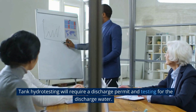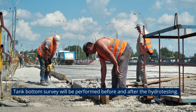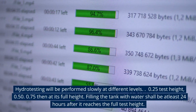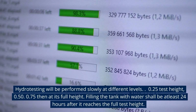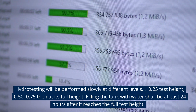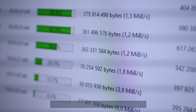Tank hydrotesting will require a discharge permit and testing for the discharge water. Tank bottom survey will be performed before and after the hydrotesting. Hydrotesting will be performed slowly at different levels: 0.25 test height, 0.50, 0.75, then at its full height. The tank shall be held filled for at least 24 hours after it reaches the full test height.